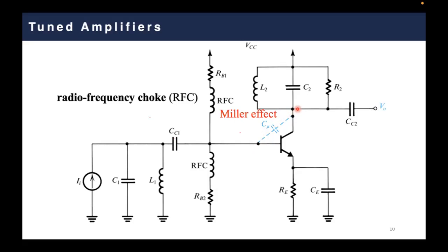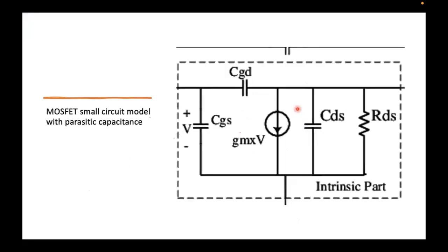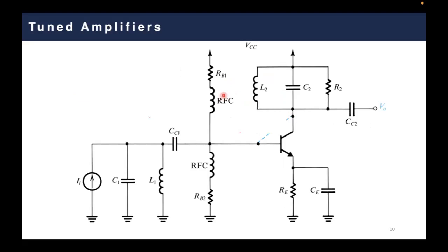how we can analyze this circuit, because basically it's very tough mathematically or circuit-wise to analyze this input-output model where there is a capacitance connecting the output to the input. So in order to make life easy, there are some mathematical or circuit tricks that you can use in order to analyze your circuit in an easy manner. So let's see now one of these tricks where you can analyze your small signal circuit model considering the Miller capacitance.